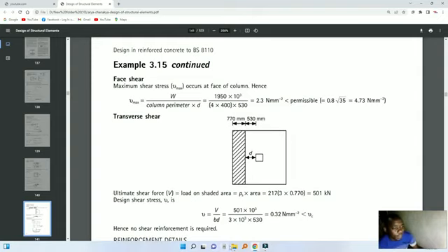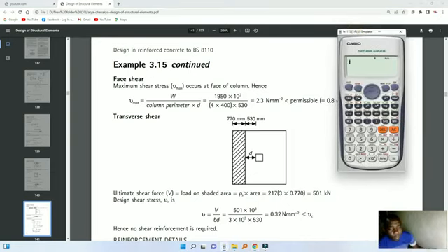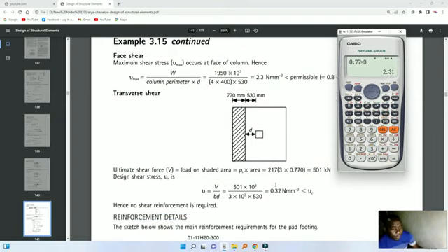0.77. Okay, let me just open up a calculator for you. Okay, so this is 0.77 meters. Then you multiply it by, from that point to that point, you multiply it by 3. So this is the area, which is 2.31 square meters. Okay, so you then multiply that area with the soil bearing pressure, which is this value PS, which is, then you multiply this number with the 217 equals, then you come up with this value here.